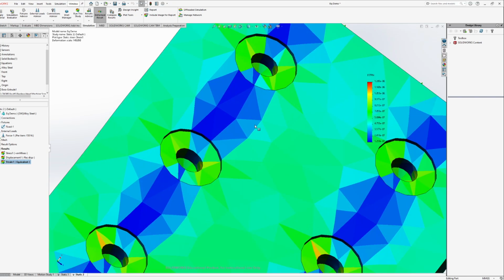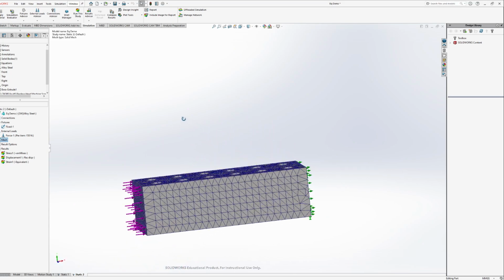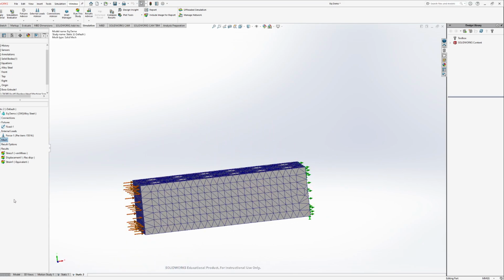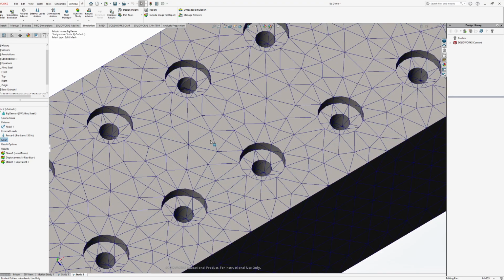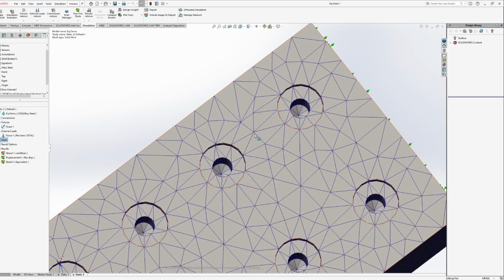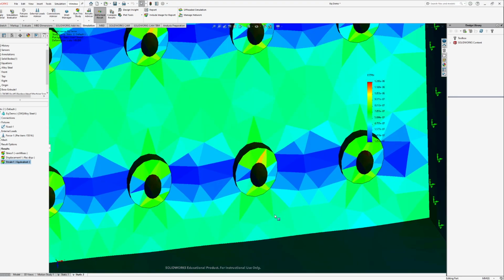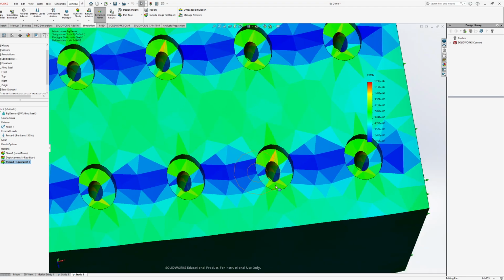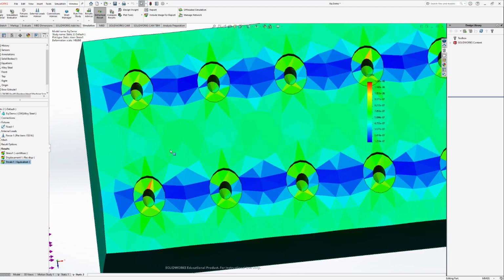geometry, like two-dimensional geometry, where all of those faces were those mesh elements. If I go back to the mesh, I think it should show it. I need to find a way. Oh, right there, show mesh. So if we look at our mesh, if you right click on it, it should be near the bottom to either show or hide the mesh. Then we can basically see that that's the general shape and consistency of those meshing elements on the surface of this mesh. So if I go back to strain, then I can pretty much see that they are deforming in some manner, and there are regions of higher strain or engineering strain than others.